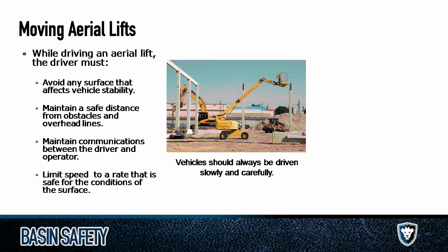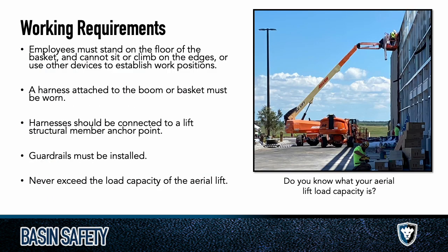When you're driving this thing, don't be driving it when you're 25 feet in the air. There is no reason for that. I'm not saying you can't move it, but what you want to do is angle it at the right angle first. So where you can articulate it or tilt the basket or whatever you have to do to get to where you're going. If your tires are not in the right spot and you need to move, get down to the equipment, move it, and then boom yourself back up. Don't do that from the air. It's a terrible idea. And don't have someone do it from the ground while you're in the air. Also a terrible idea. You want to be in control of that thing.